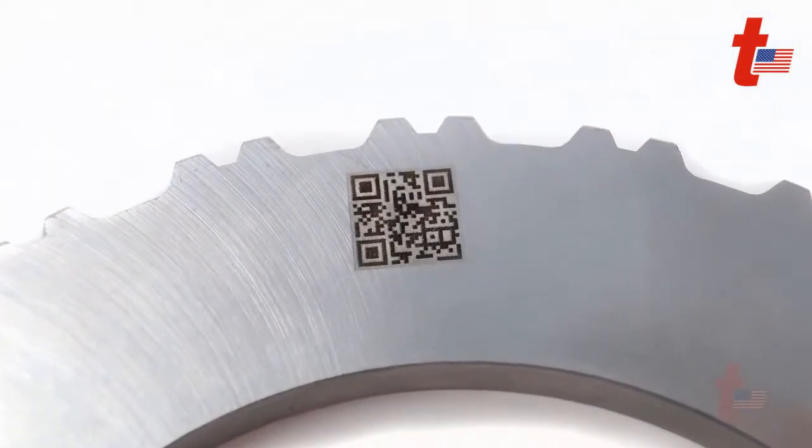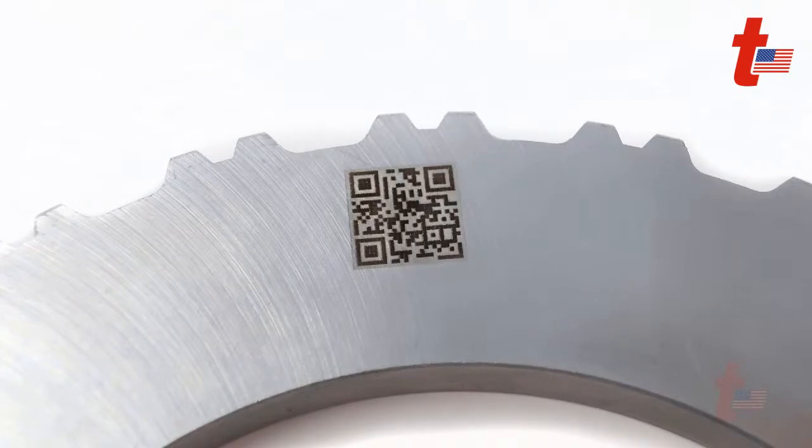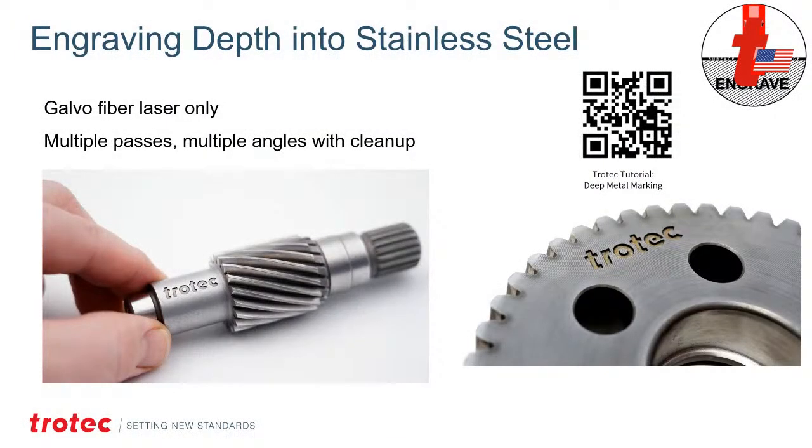Again, the Galvo is the ideal solution, especially if you want to produce any depth. Flatbed systems will not produce depth. I don't care how many passes you take. You may be able to see 1/1000th of an inch or so, maybe 2, but it's never going to be the same as a Galvo fiber. If you do want depth like this, the Galvo fiber is ideal because not only does it produce a faster response to the laser, it allows the laser to go in multiple angles as it's doing multiple passes, and in between each pass it does what's called a cleanup pass.